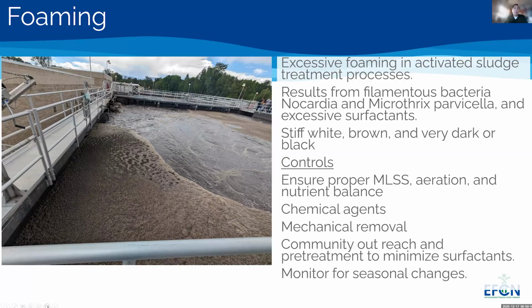With these kinds of issues, foaming is especially notable as occurring during seasonal changes, when there's a flip in the weather that does something unusual to our biology and our activated sludge. And that's the time when you want to keep an eye out the most.